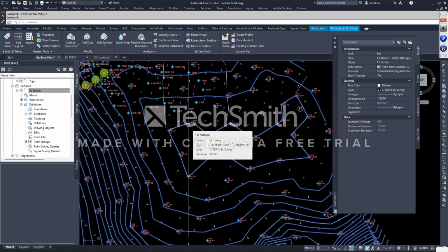When I need to get something out of the surface and have it be two-dimensional polyline work or three-dimensional polylines, but I don't want to explode the surface, because it's an object in Civil3D. Every object in Civil3D can be exploded, and the first time you explode it, it becomes a block. After that, you explode it one more time, and it becomes live contours, which would be polylines or line work, whatever the block is made up of, based on the style that is currently shown. When you explode something in Civil3D, it disappears from the tool space. You have to recreate it.